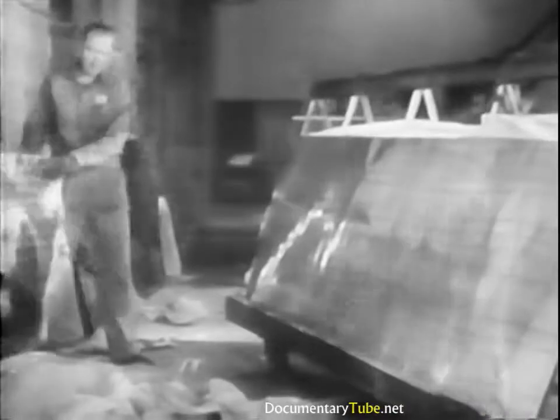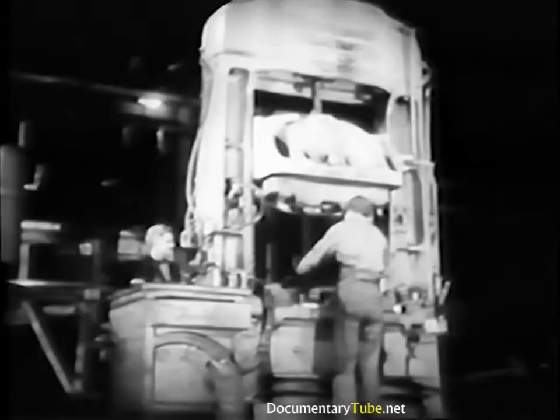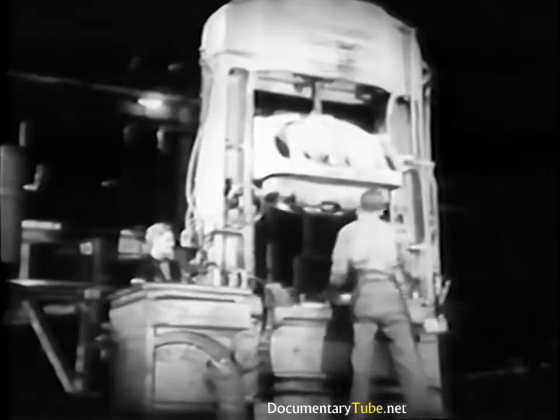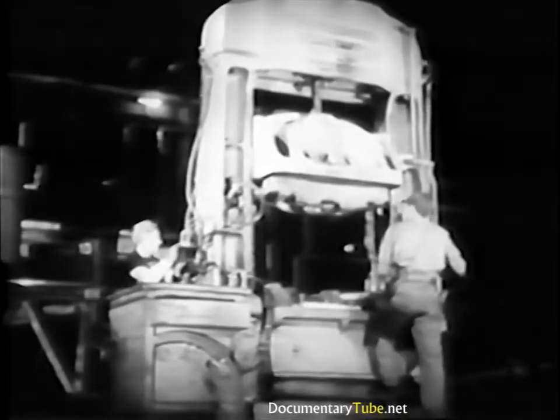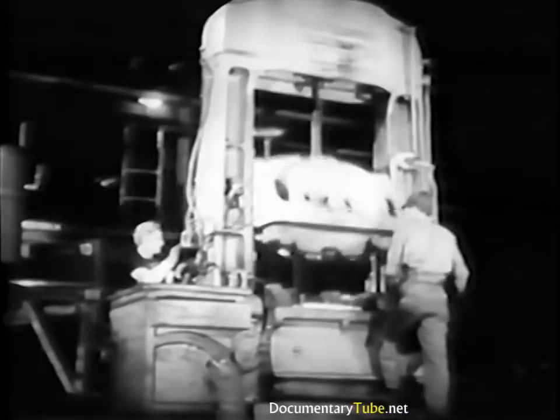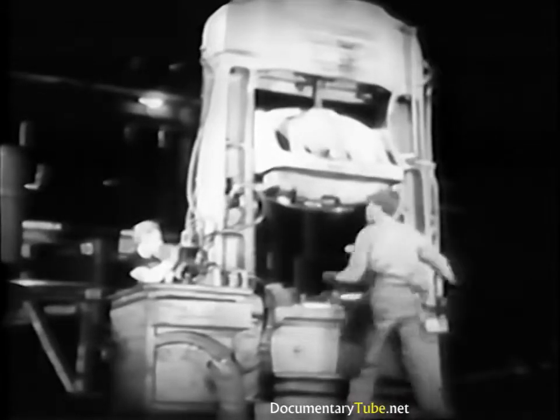The primary function of the various forming methods is to convert the aluminum alloys into desired shapes. Strain hardening accompanies these cold working operations, and in extreme cases, annealing between operations may become necessary.